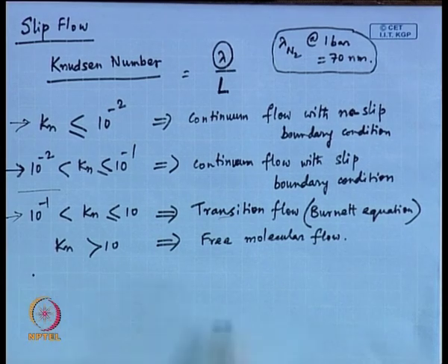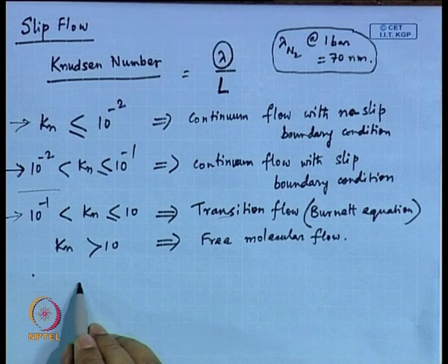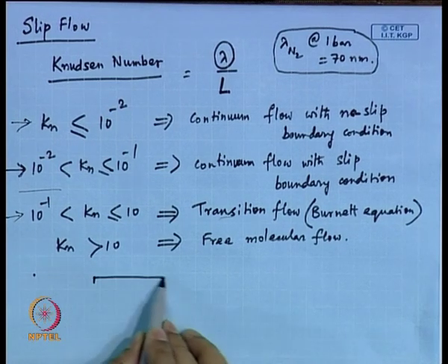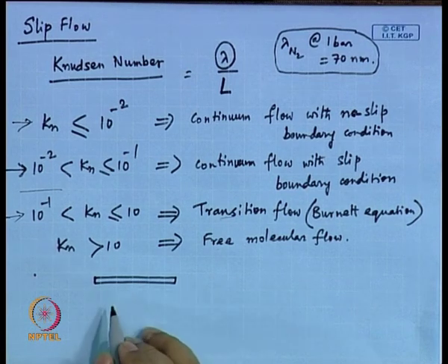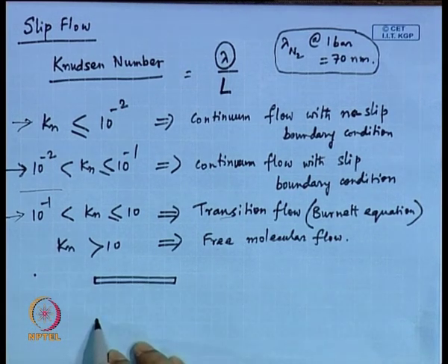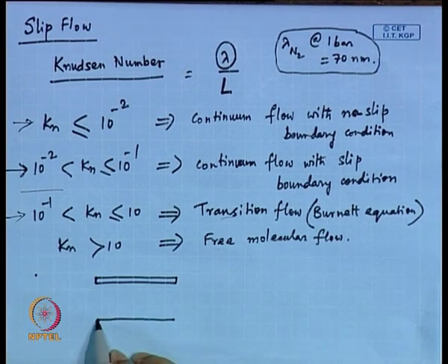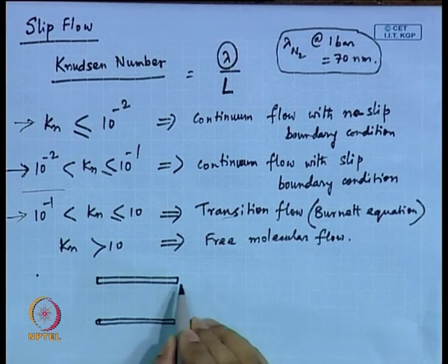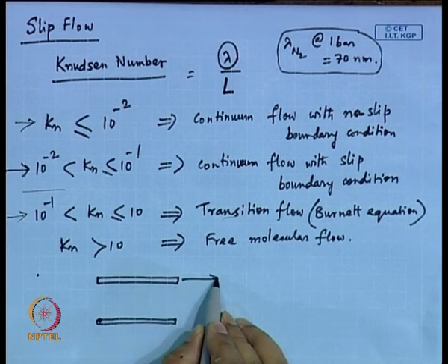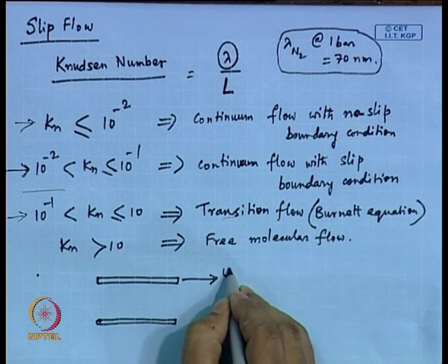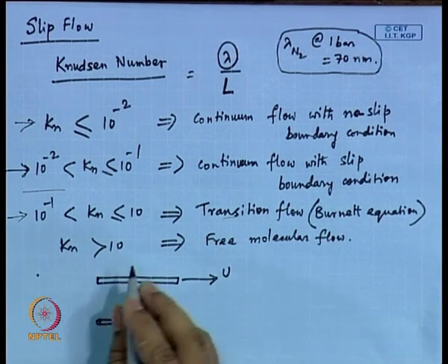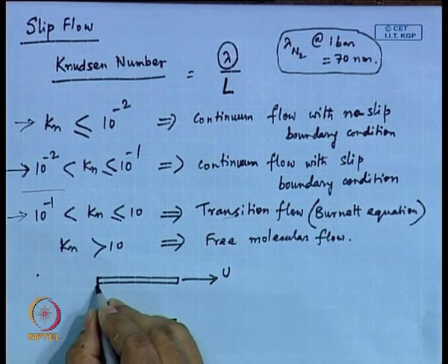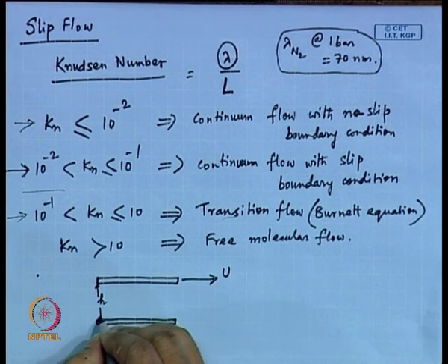Couette flow. Micro Couette flow means this: you have already studied it when we first studied the definition of viscosity. The first thing we studied is those two plates, right? One plate is fixed and the other plate is moving at a constant velocity u, and the separation between these two plates is h.